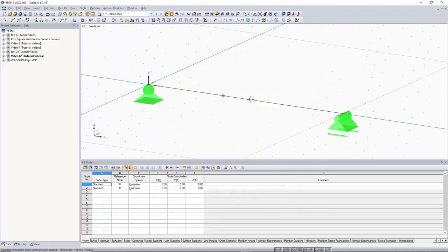We'll click OK, and now we can click on our line in the graphic, and you can see what these 2 point loads will look like graphically. We have 25% away from the start to the first point load, and then 35% between them.